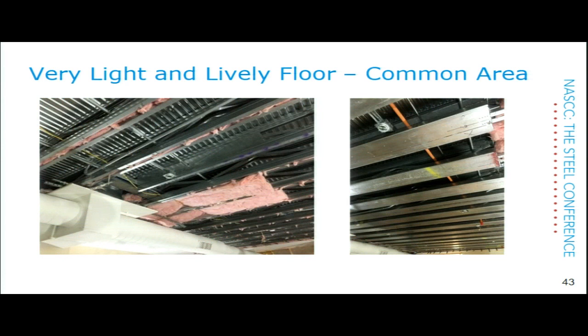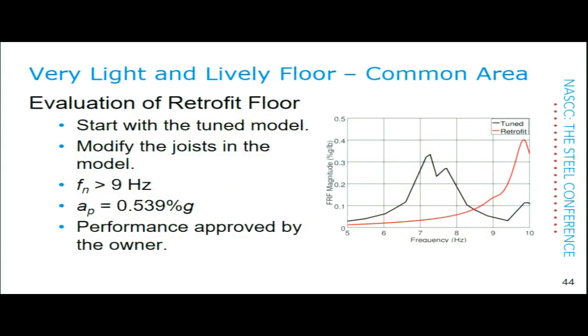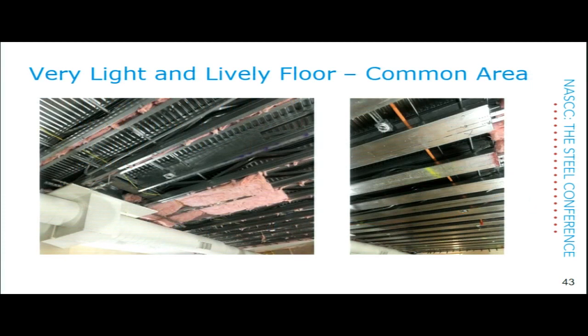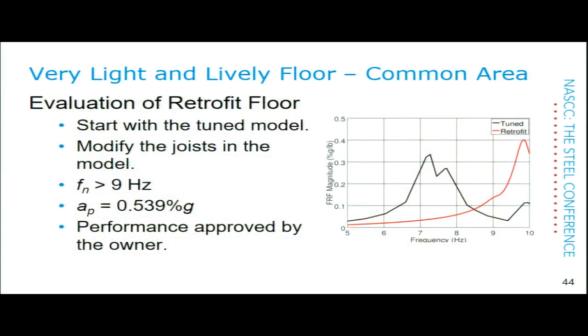Okay, so here's a picture. We have on the left the unretrofit. You can see the trusses there, and on the right you see we have these 12-inch channels, the heaviest ones we could get, screwed in there, and you probably can't see the top chord channels as well. So we have all those in there just to get a lot more mass and stiffness. Our backup, by the way, if this didn't do it, was to take rebar and put padding on them and put that perpendicular, just keep adding rebar in pieces until we had enough mass that way. But we're trying anything. So this is going to work.